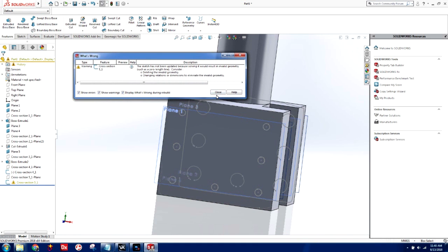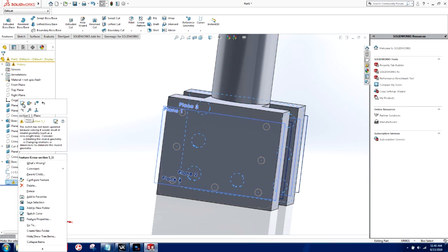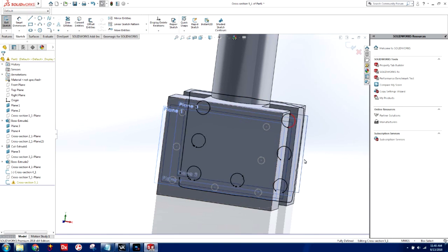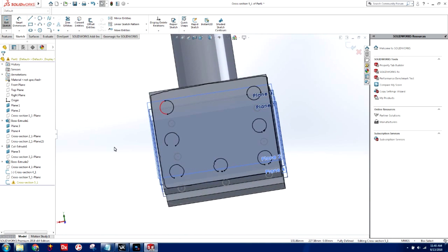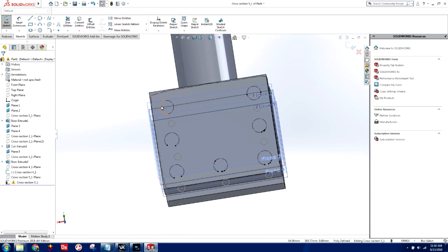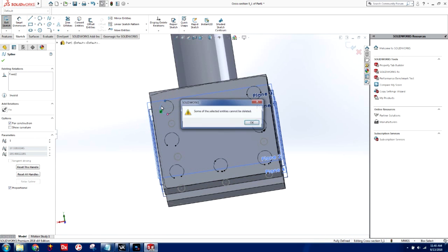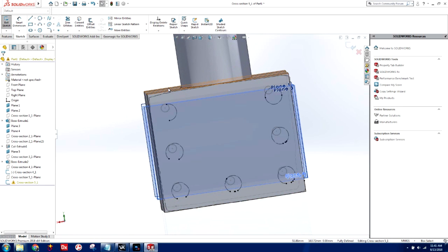And oh, looks like I got an error in this. Looks like one of those polylines may have gotten over-constrained. Let's see. Yep, that's exactly what happened. So that half a circle in red there just got over constrained. No big deal. I'll convert it to construction, select on that, and hit delete. Yep, that fixed it. Only need half of it anyway.